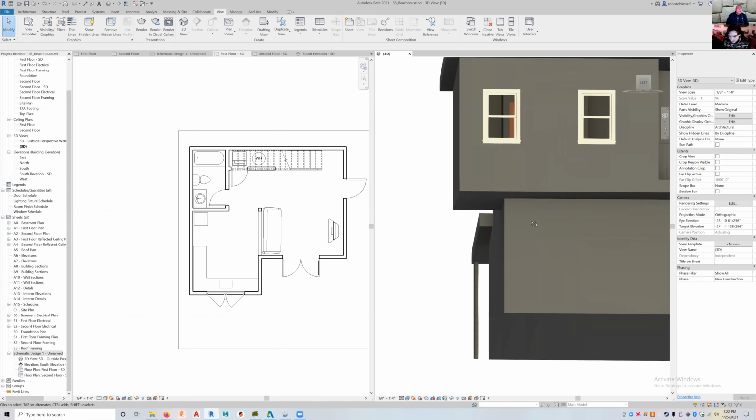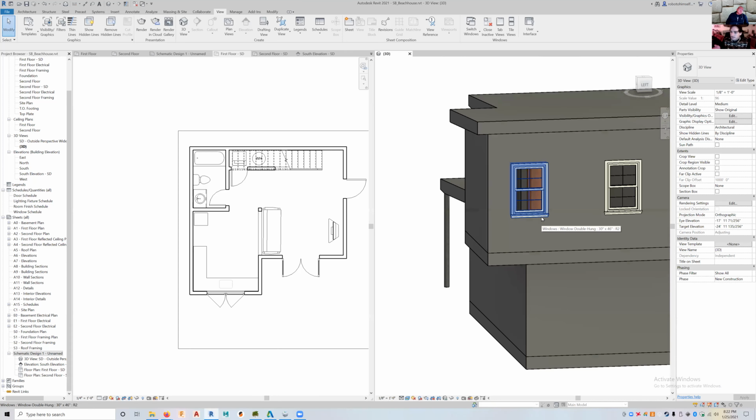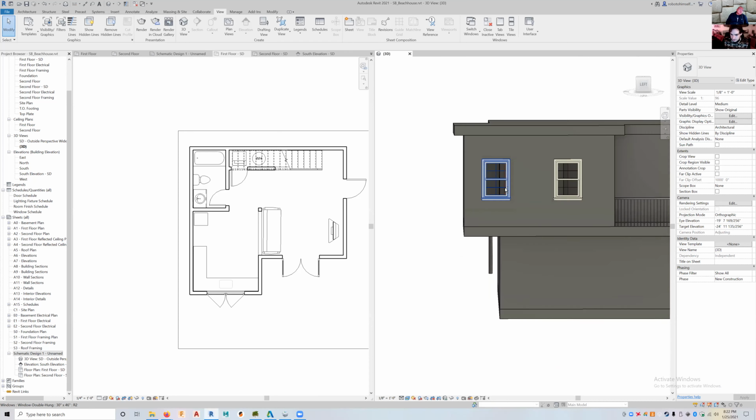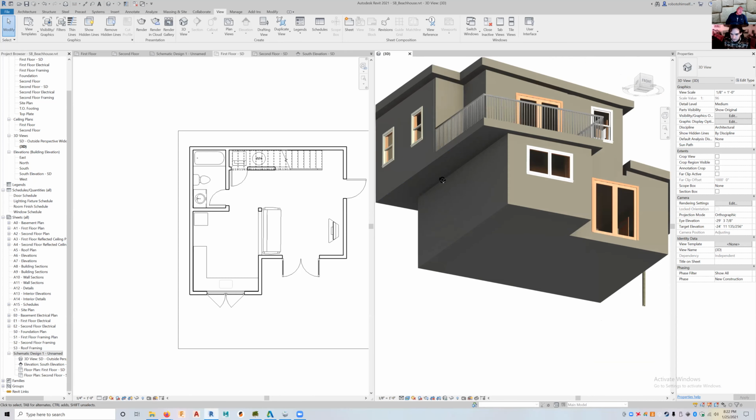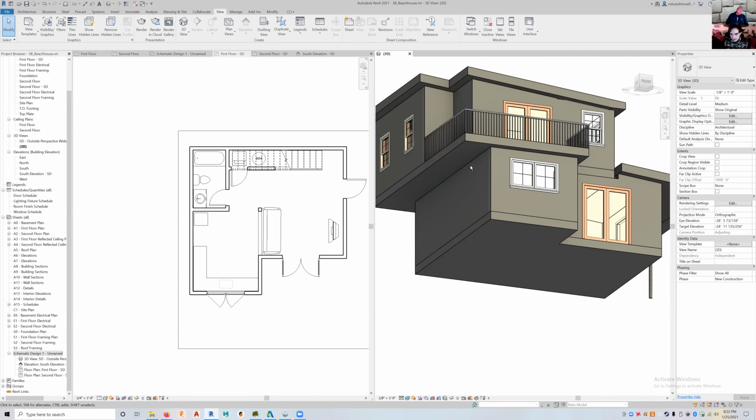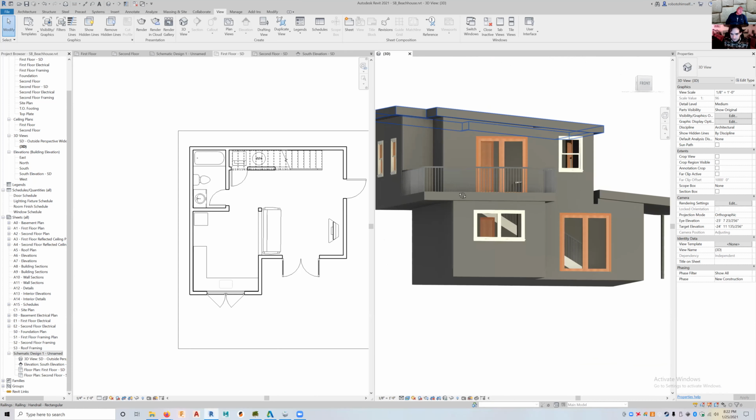Yeah, you can do that. It's 4 times the joist height or something. I looked it up. When you cantilever, the idea is that you have 1/3 cantilevering and 2/3 inside. Right, so it's not coming out too far. Yeah, that's right. So it works.